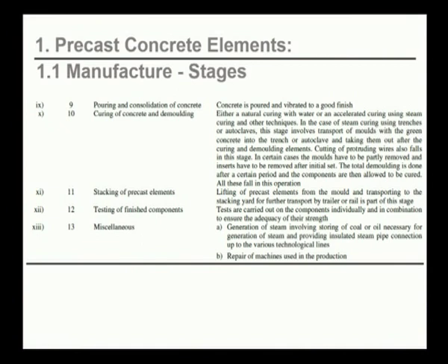The 9th stage is pouring and consolidation of concrete. Concrete is poured and then vibrated to achieve a good finish. The 10th is curing of concrete and demolding. Either a natural curing with water or an accelerated curing using steam curing and other techniques can be done.